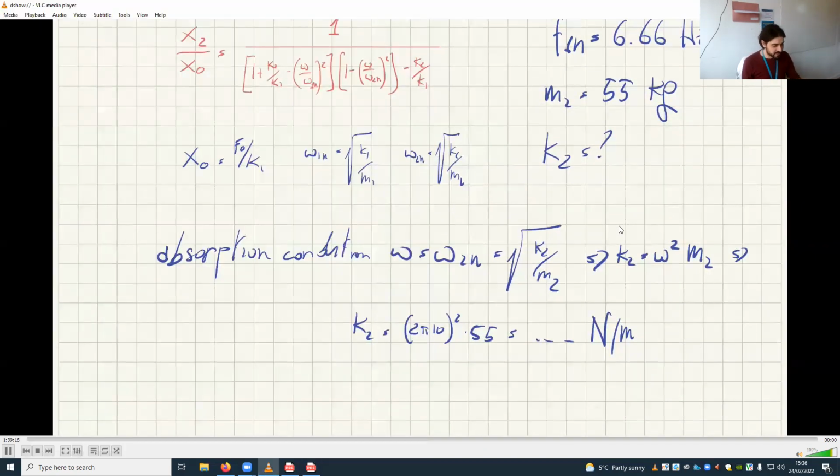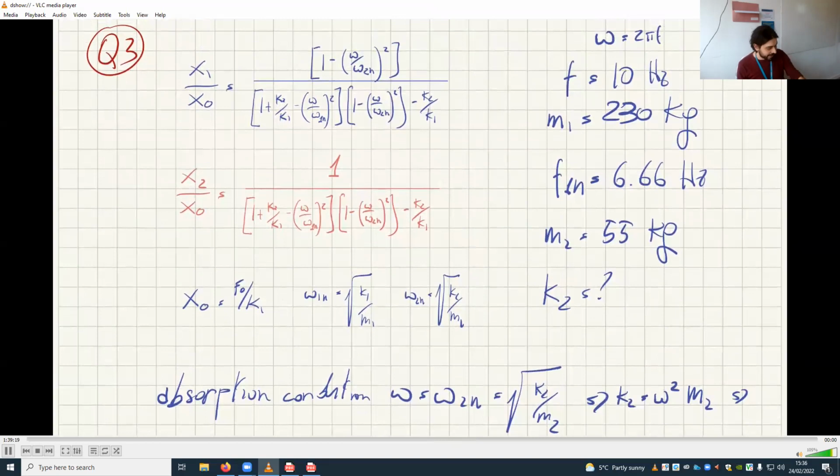Okay, now the question is, let's look at this equation again. Now we know that at omega, with this omega fitted in, this would be 0. Easy. But when will this explode instead? So the denominator must be 0 now. So this thing will explode when the denominator is 0. So we have to solve for the omegas, the unknown driving frequencies that make this thing equal to 0.